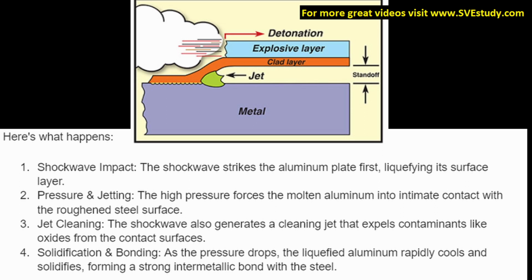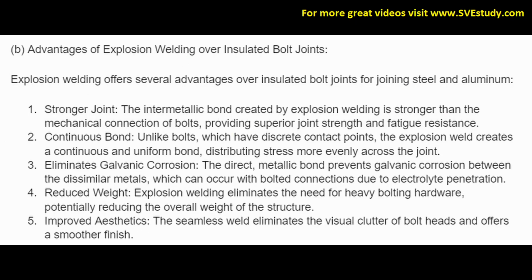3. Jet cleaning. The shock wave also generates a cleaning jet that expels contaminants like oxides from the contact surfaces. 4. Solidification and bonding. As the pressure drops, the liquefied aluminium rapidly cools and solidifies, forming a strong intermetallic bond with the steel.